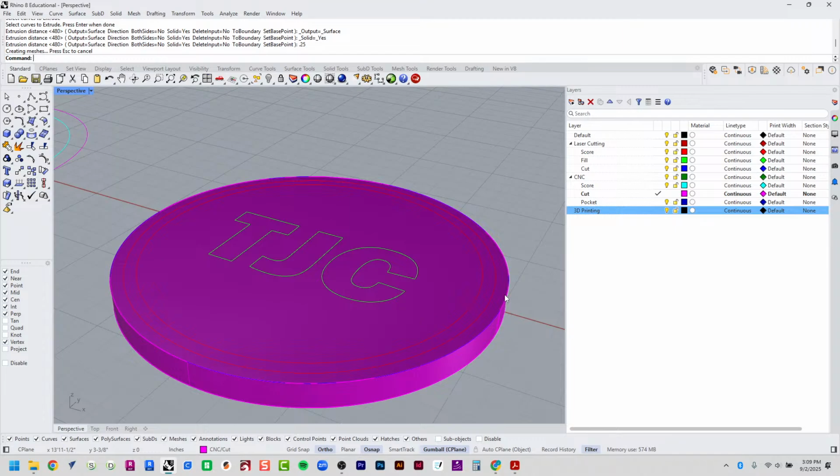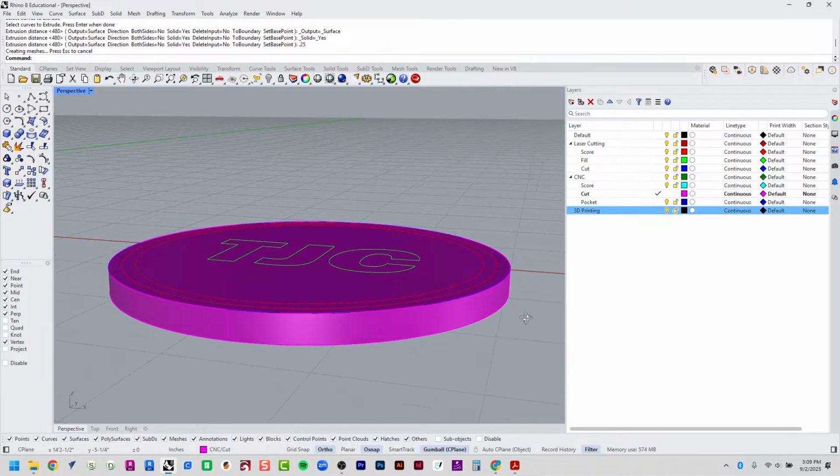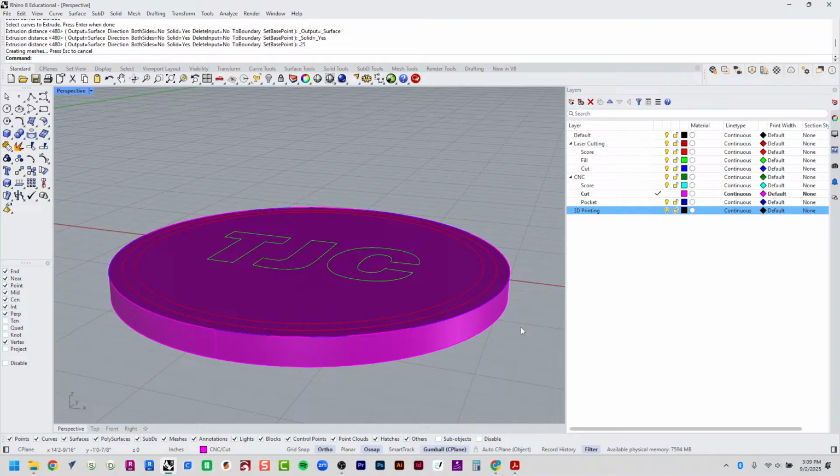So what can we do? I'm going to start to be subtractive now. Okay? We're going to start to take away from this basic shape. And the shapes we're going to use to do it are these ones here. Okay? So notice that these curves are sitting atop the face of this cylinder, right? The top face of this cylinder.